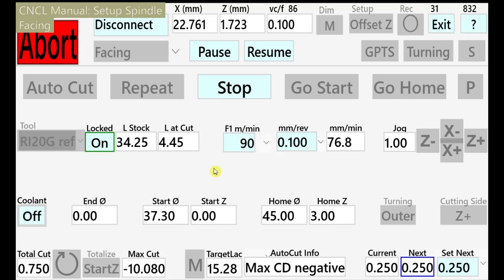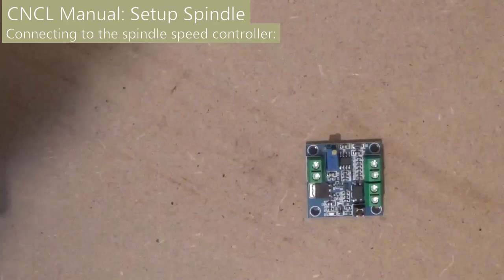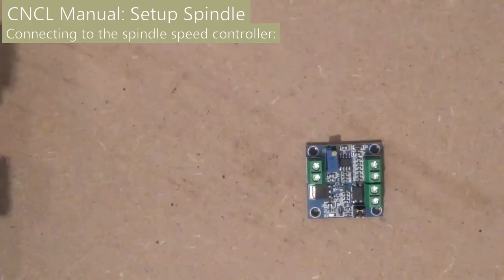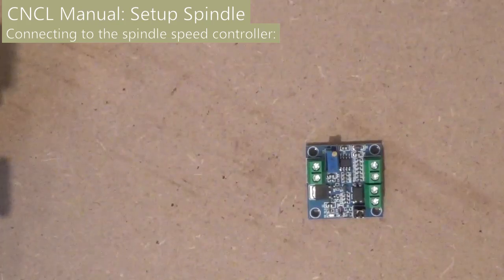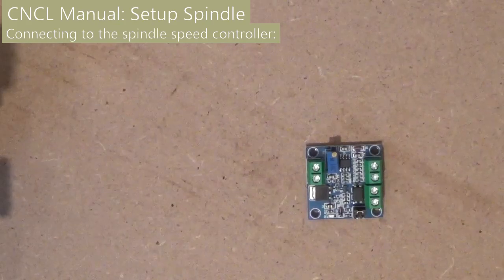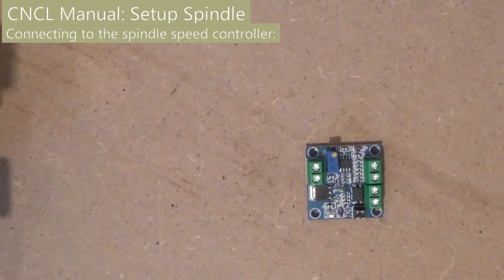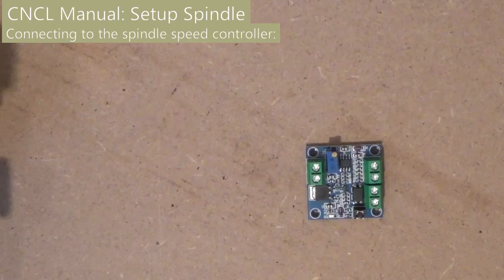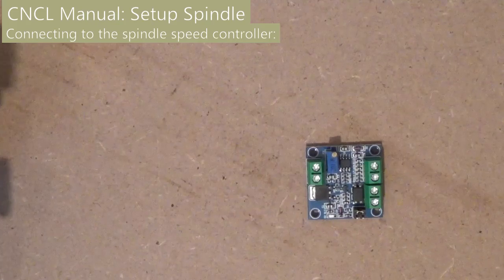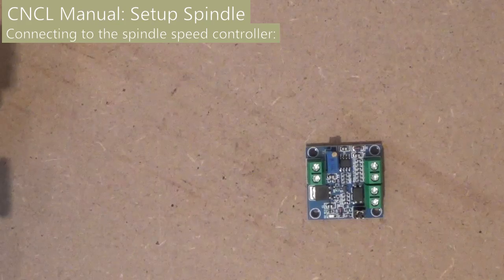In general, to get repeatable results, I run the spindle in speed mode and the feed in feed per revolution mode. To use spindle speed control, you have to connect the CNC controller's spindle speed output to your lathe spindle speed controller input. Most CNC controllers output a PWM signal. That is a pulse width modulated signal.